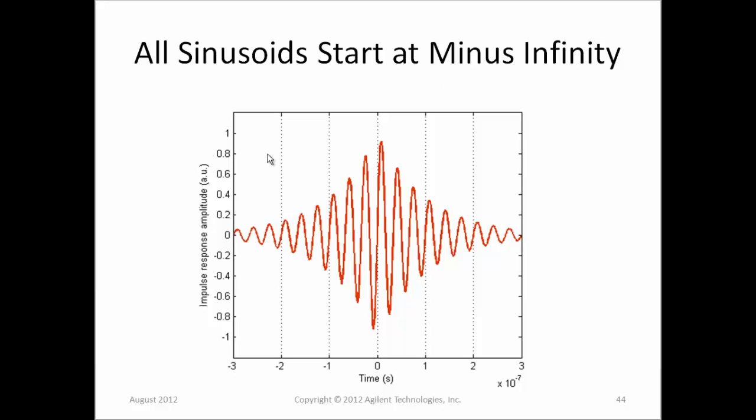How could you possibly add up all these sine waves and cos waves and get it to exactly cancel out everywhere from minus infinity to 0, and yet still have a positive response beyond that? You think it might be impossible to build an impulse response that is causal out of sine waves, because the material you have to work with, every single one of them has a finite value at minus infinity. How can you possibly build an impulse response out of sine waves and cos waves?